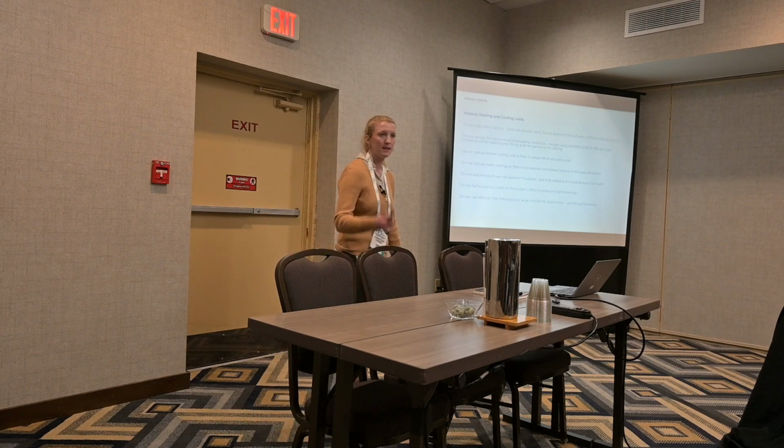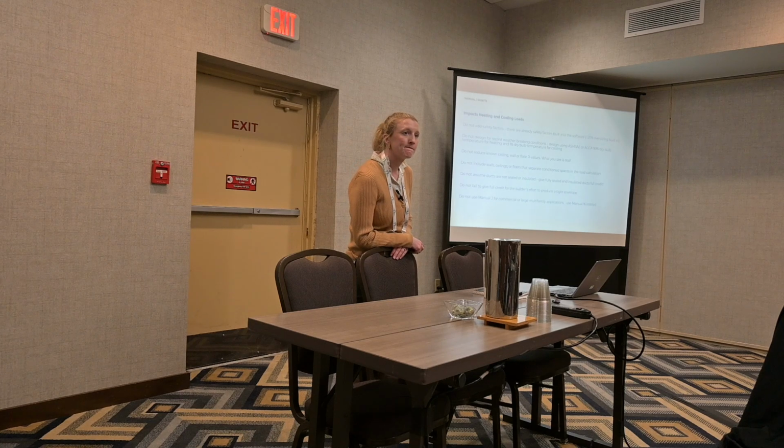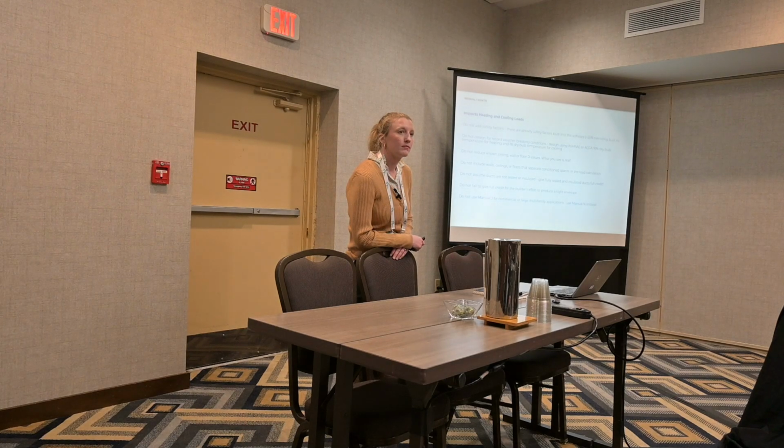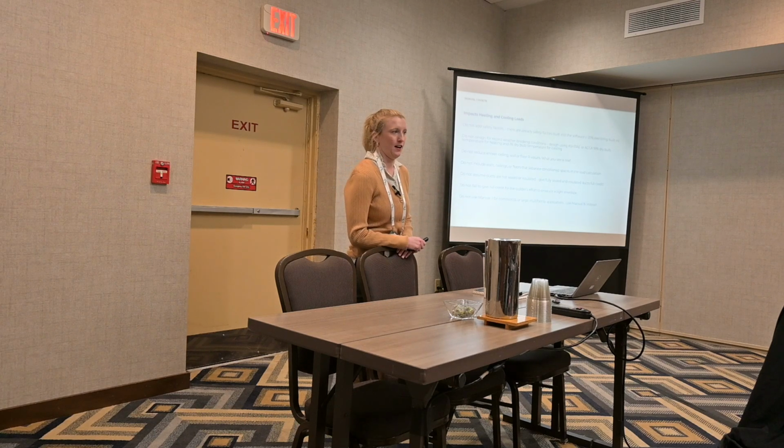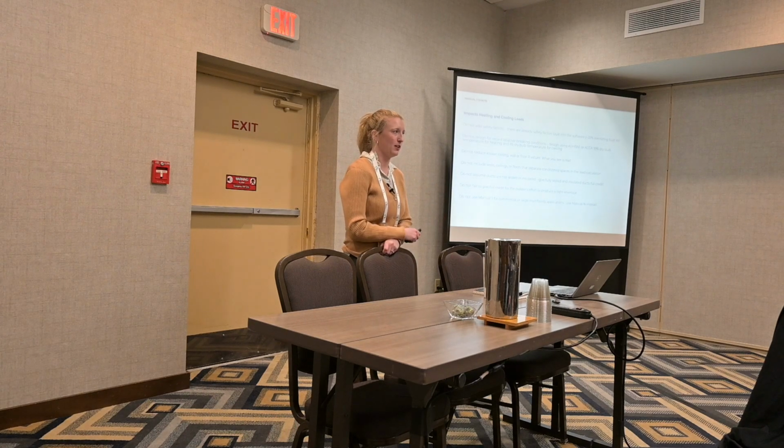I've seen heat pump water heaters with the output ducted through the rim joist outside, so the basement wouldn't be cooled down, especially in winter. If it's not going to be part of the conditioned envelope, and it's not going to be impacted by what the heat pump's putting out, then you wouldn't. Even so, that's still a heat sink.